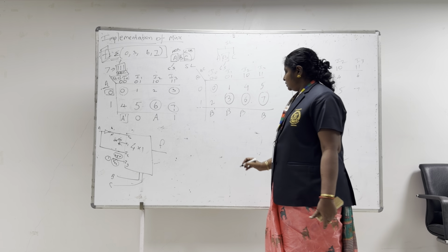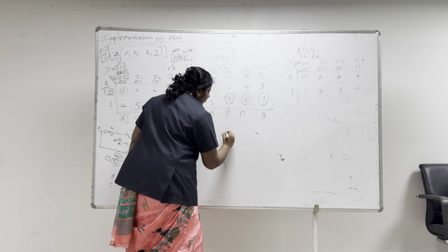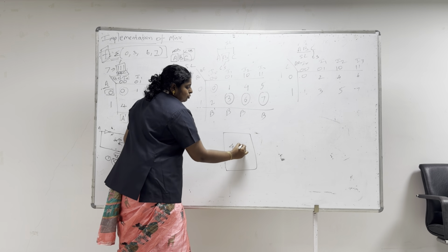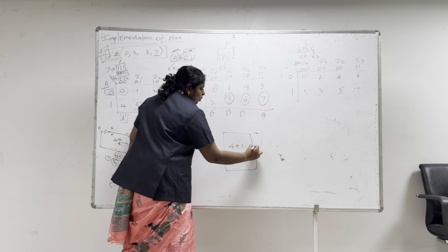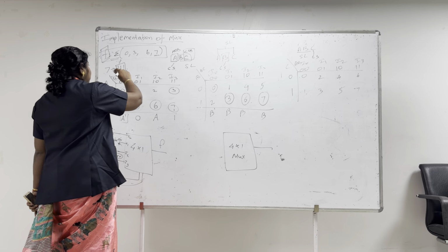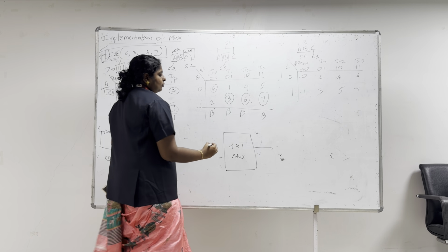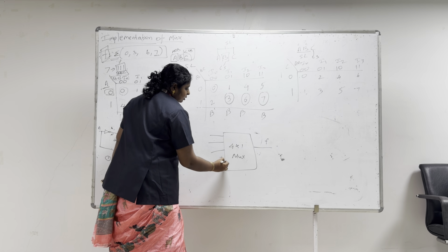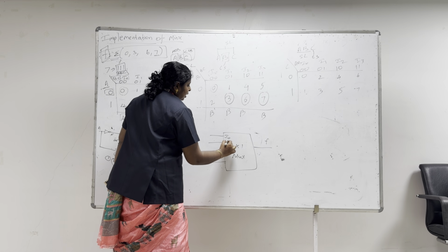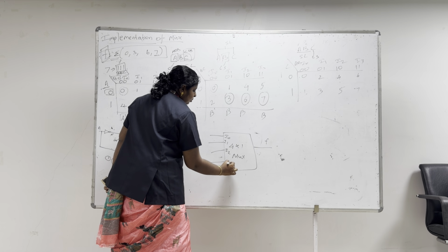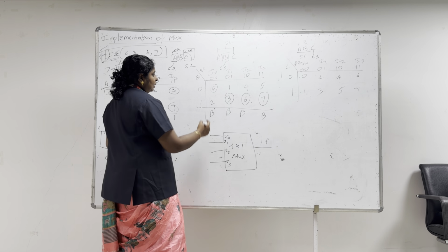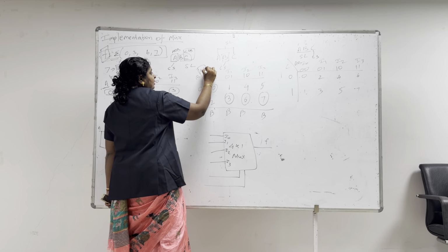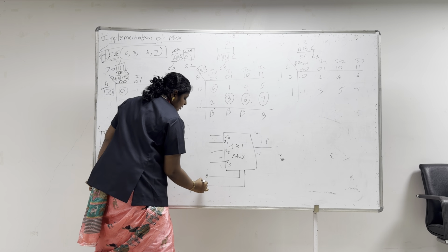Okay, so now let's design this the same way, only 4 inputs, I0, I1, I2, I3, therefore a 4 cross 1 mux. So one output, as I defined earlier, the output is the function given to you, f. 4 inputs, I0, I1, I2, I3. And my select lines over here, these are the select lines, right? A and C, A and C.